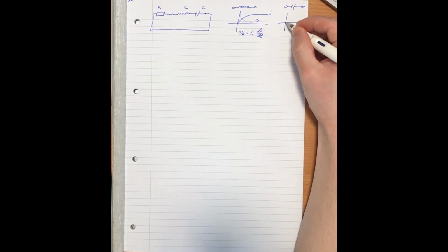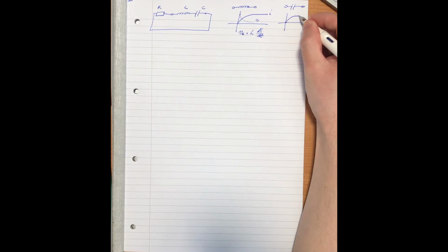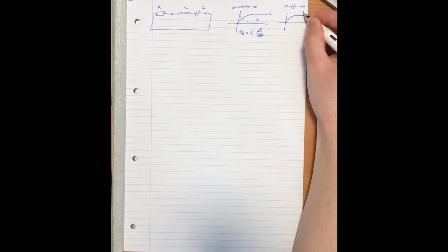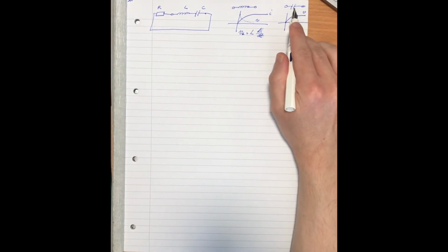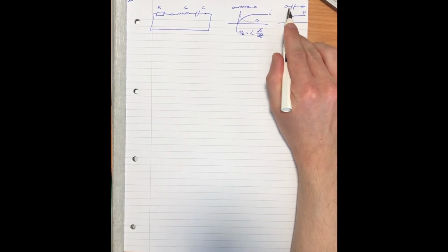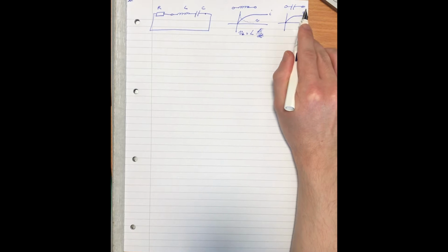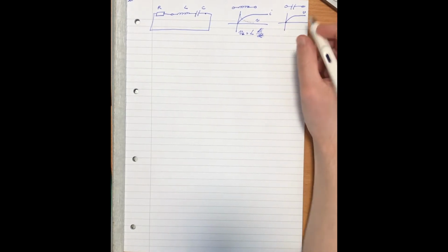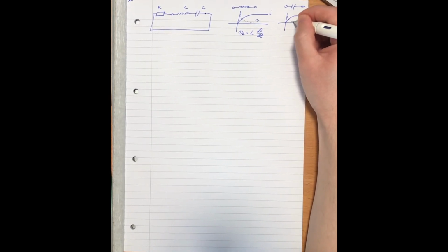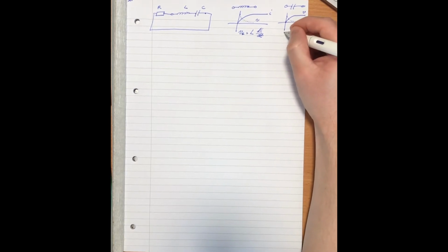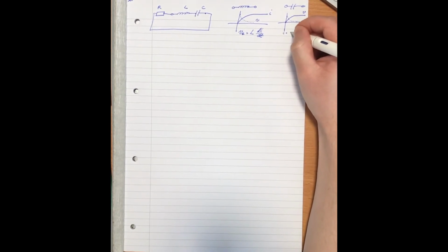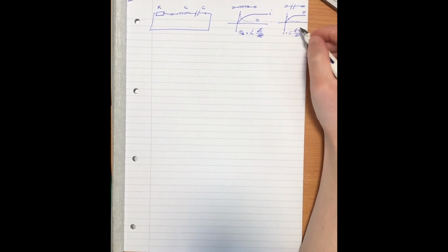we can say that initially the voltage is going to be zero, but then it's going to build up and build up until it reaches a maximum where the potential difference between the two plates will not increase anymore. And at that point, no electrons will be able to flow in either direction. And initially, the current's going to look something like that. So we can say for a capacitor, I equals C dVc by dt, where Vc is the capacitor voltage.